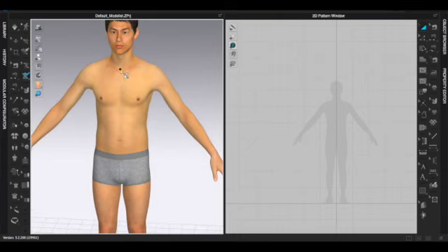drawing my lines. So I'm going to start here at the base of the neck, and you have all these options. You could do a custom measurement if you wanted to, or just draw straight. I'm just going to draw straight. Another trick is if you hold down the shift key, then it will give you the perpendicular and parallel lines, so you know that you're heading straight and you aren't veering off. So I'm going to hold down the shift key, come down to his belly button and click. And then I can do the same, working my way around the body.